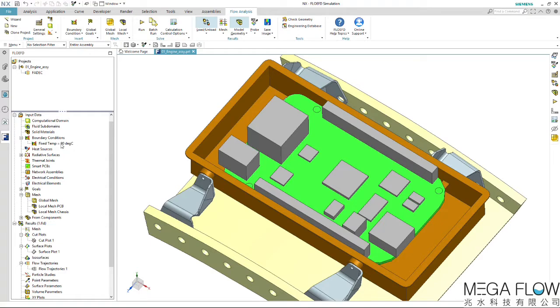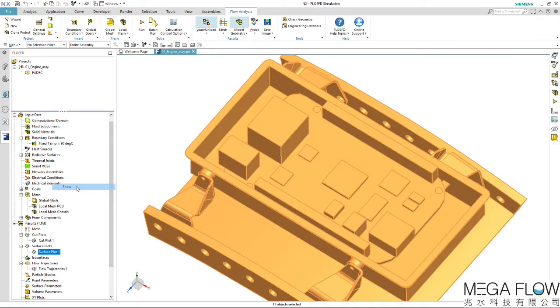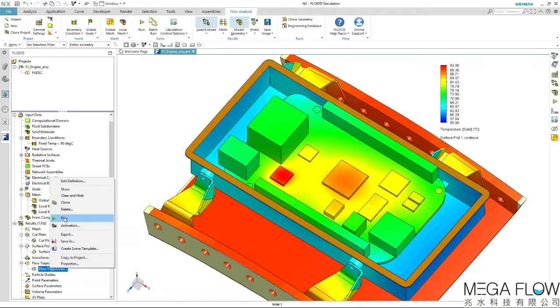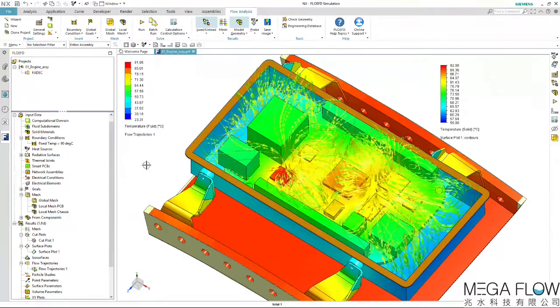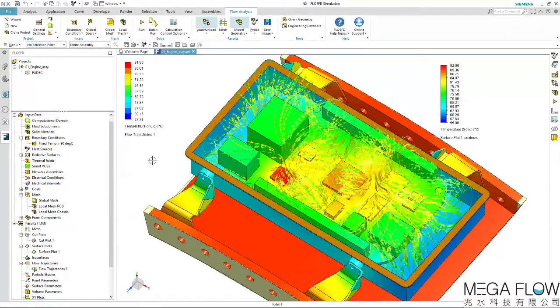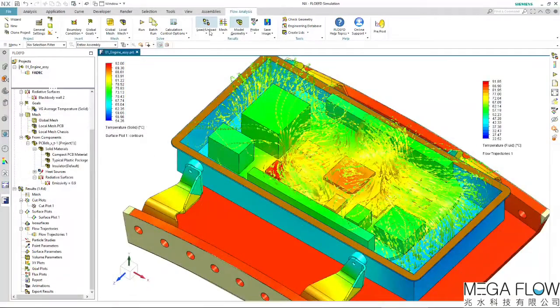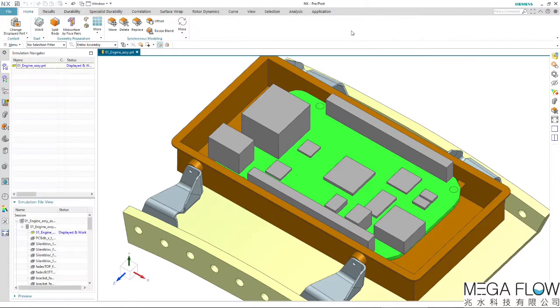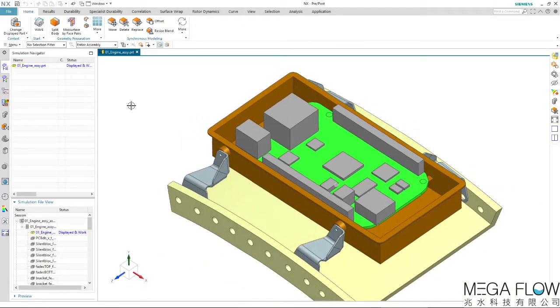A fixed temperature boundary condition of 90 degrees C is set on the housing. A full 3D CFD thermal simulation in SimCenter FloEFD predicts operating component temperatures as well as PCB temperatures. Natural convection airflow distribution within the FADEC enclosure is also predicted. The FloEFD results are unloaded and the SimCenter 3D pre-post interface started directly on the same model geometry without leaving the Siemens NX session.